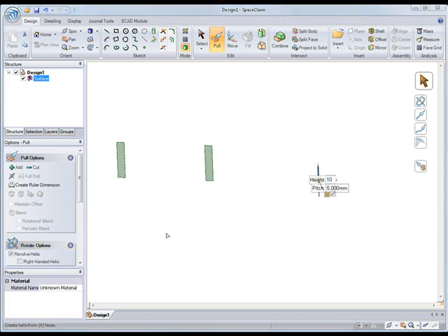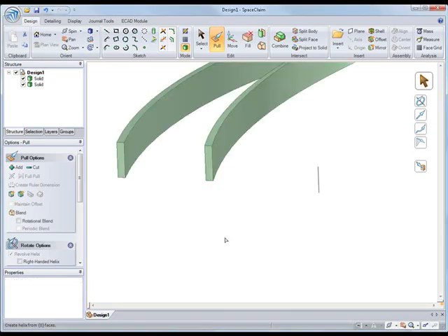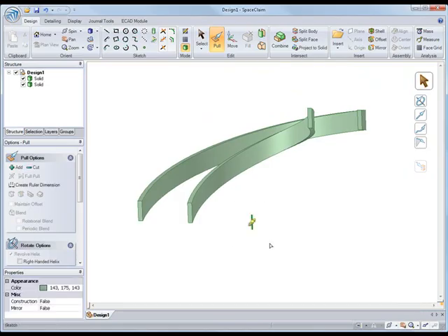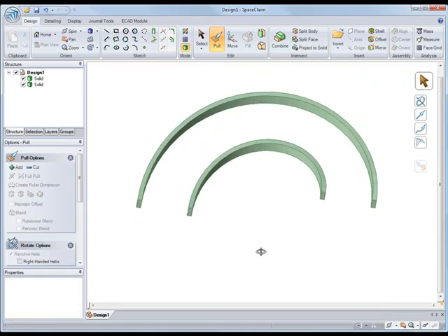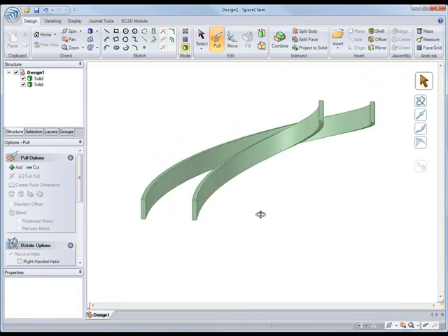Now let's enter in the height. So we want that to be 10 feet, so we'll enter that. And now the pitch. So that's basically how high it goes when it makes a full revolution. So I want it to go 180 degrees, so I'm going to type in 2 times 10 feet, just in case we had to do something more difficult, when I could have typed in 20. So now that it revolves around, we can get rid of that axis. And we have it going 180 degrees around, 10 feet up.